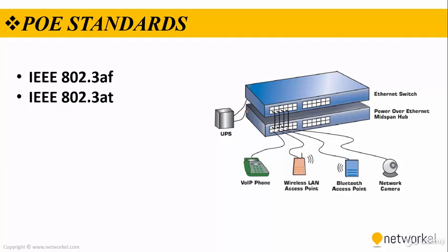We have two PoE standards, and they are IEEE 802.3af and 3at. Let's start with 3af first. This standard provides interoperability between different vendors. In this standard, the devices are supplied with DC power up to 15.4 watts.